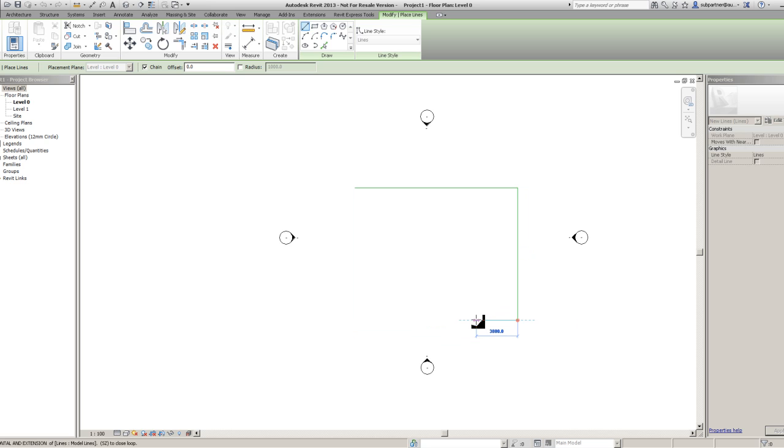Okay, this is all basic stuff, I know it is. But let's just go across just here. Now let's just say this time we want to come across, I don't know, 9 meters. We're going to type 9, but instead of writing 9,000, we're going to write 9M. Then press enter. And if I move the mouse across, it will automatically convert it to 9,000 millimeters. Okay, so a nice little feature.